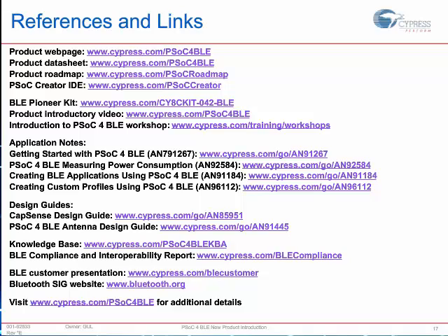In addition, the antenna designs of the PCB antenna that we have implemented in our development kit that you evaluate with are freely available to all users. You can download those schematics, and feel free to reuse our antenna designs because our antenna designs have already been qualified by the FCC. So you have a very high degree of confidence that if you repeat or copy our antenna designs, and feel free to do so, you will pass FCC qualification with very little issues.